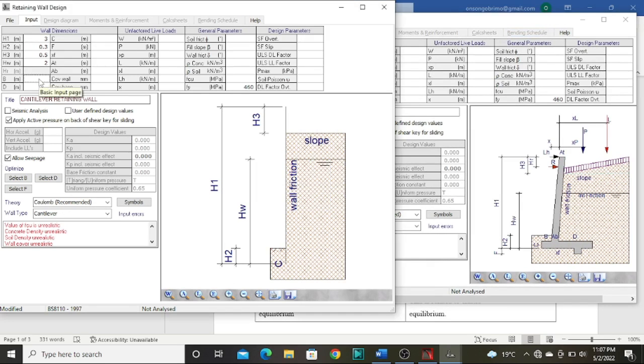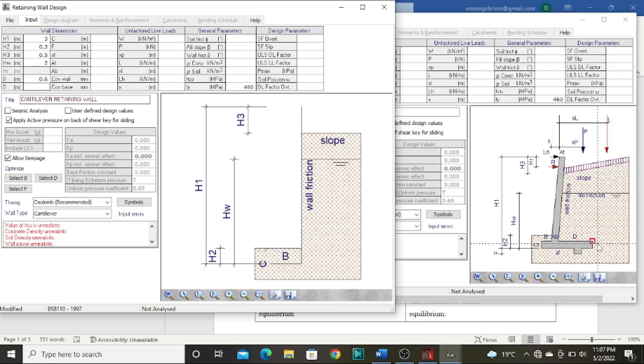We also go to B. B is the horizontal base dimension in front of the wall. As you can observe, it is the distance from this to that. Let's assume we have 600 millimeters at that section, that is 0.6 meters. And D is the section at the back, the horizontal base dimension at the back of the wall in meters. Let me assume I have 2.